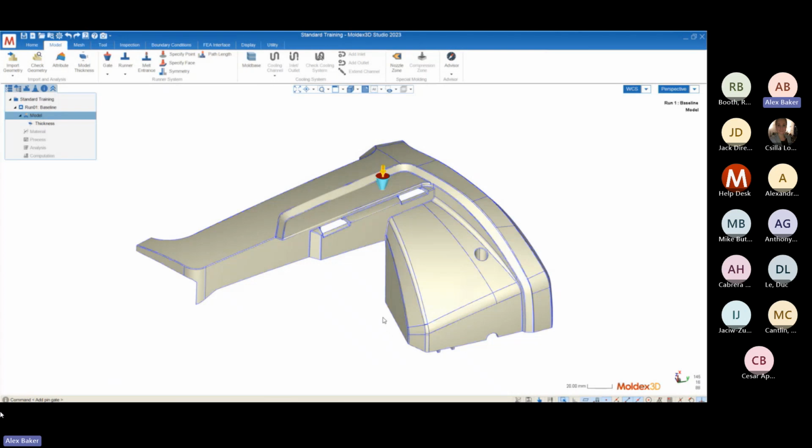If the surface temperature is completely uniform, there's going to be no differential temperature effect in our warpage calculation, and that's going to create a much lower magnitude of warpage from the simulation than what you would see in reality.